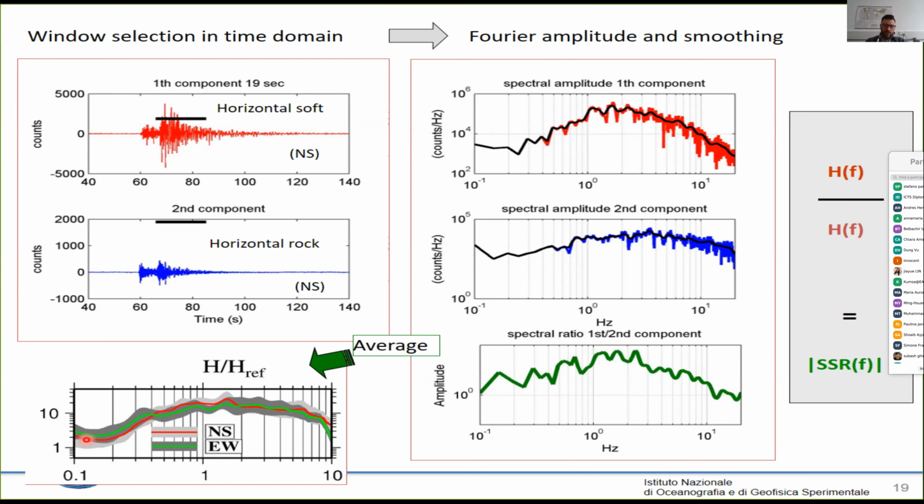But what is really striking, if you remember from the previous lectures, this site response when we only consider the vertical propagation of waves, and especially of SH waves, what we observe here is that we have a sort of first peak that corresponds to the resonance frequency of the site.